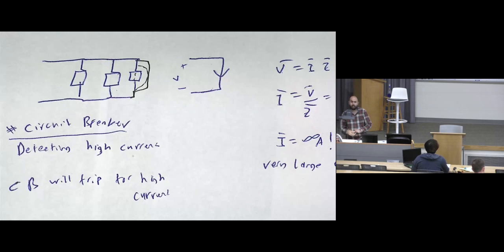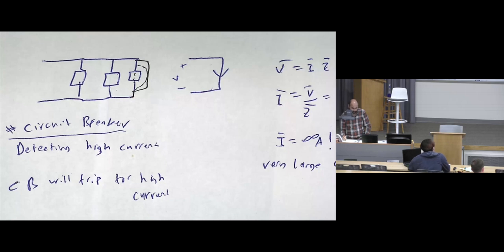And it's detecting the high currents in milliseconds. So if, for example, the current exceeds 35 amperes or 50 amperes within, let me say, 5 milliseconds, then it will trip. So within milliseconds, it should trip, and it should take this action to avoid the damage from happening.